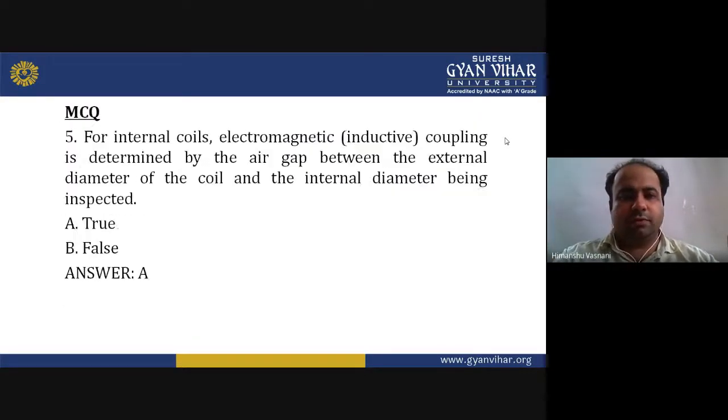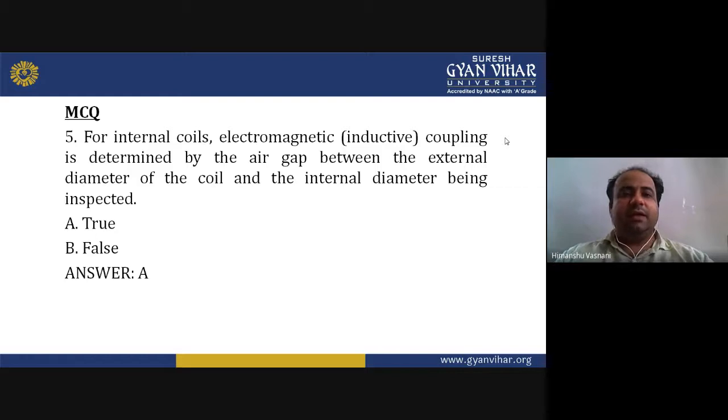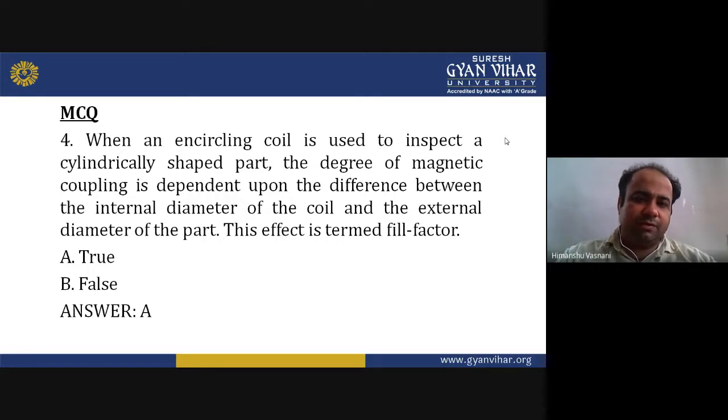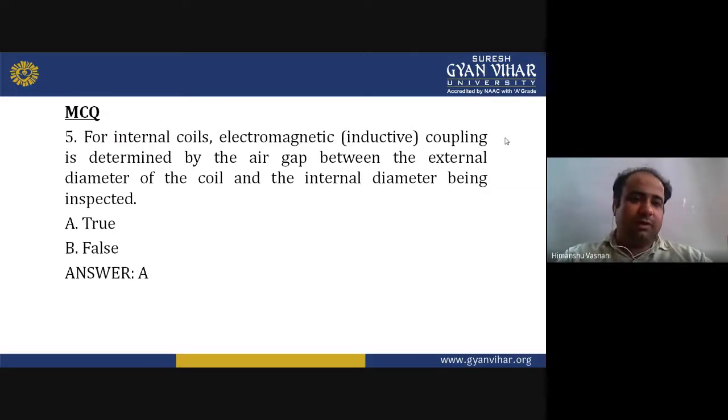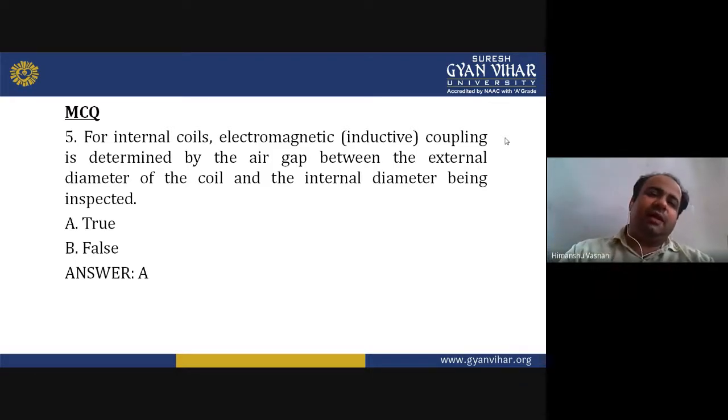Now, for internal coils, electromagnetic inductive coupling is determined by the air gap between the external diameter of the coil and the internal diameter being inspected. You can see that if you talk about the fill factor, it was a different thing. But here, in the next question, they're saying that for internal coils, electromagnetic inductive coupling is determined by the air gap between the external diameter of the coil and the internal diameter being inspected. So in this case, it's just true. For internal coils, it is true. Answer is A.